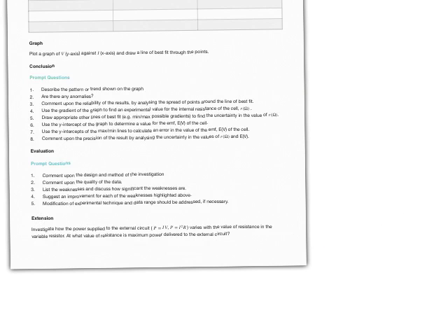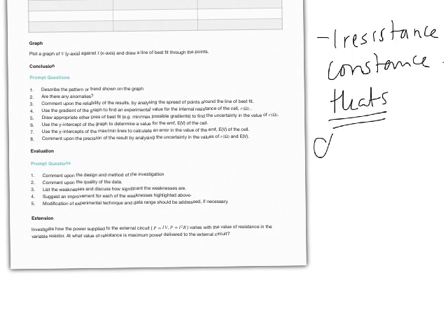In terms of the evaluation, there's all kinds of things you can think about. We have internal resistance is assumed to be constant, but as the power supply heats up, then you get a change in internal resistance. This would cause a slight curve. Okay, that might be something you've seen.